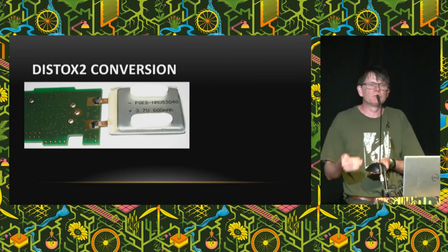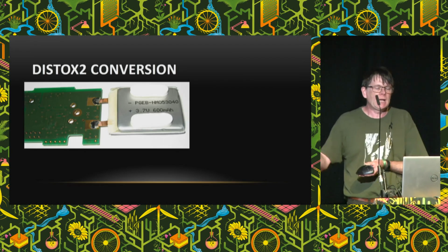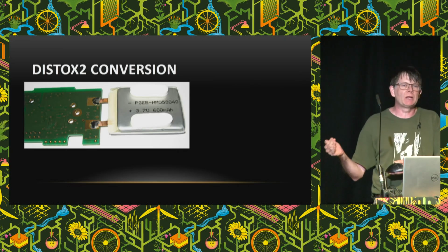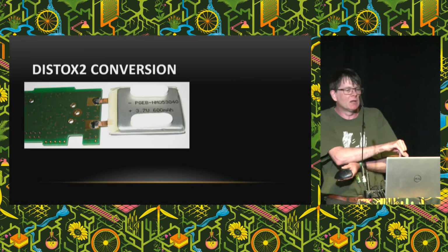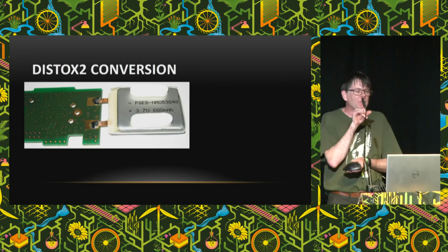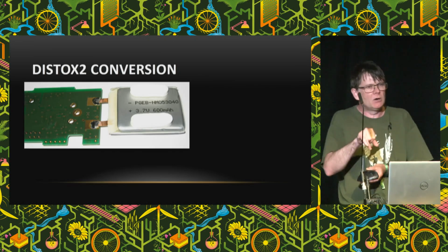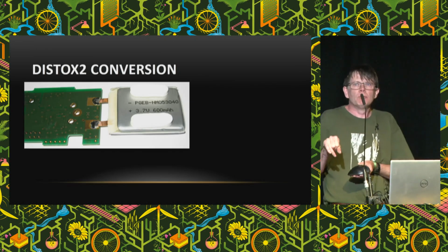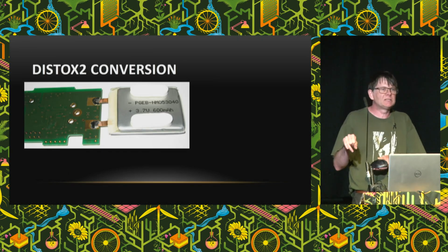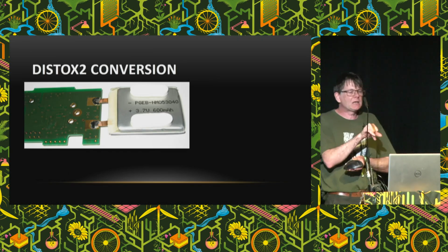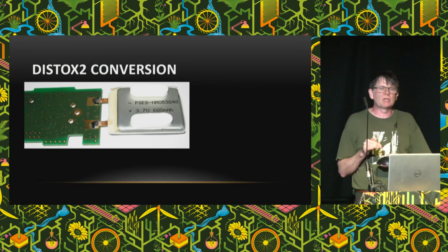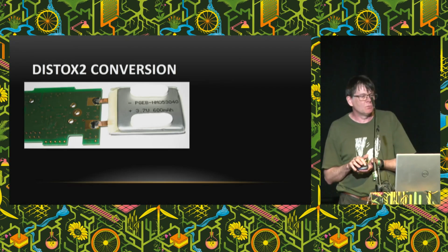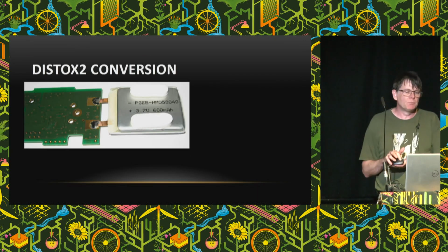The second version, there wasn't room for a daughter board, so the app designed a completely custom PCB that replaced the entire internals, apart from the laser unit of the Leica. So this custom mainboard had a battery soldered onto it, and to get that half degree accuracy of compass required an environment that was very low magnetic interference. And so these were medically non-magnetic lithium polymer batteries, made by a medical devices company in the US. And we would get these in, solder them onto the board.